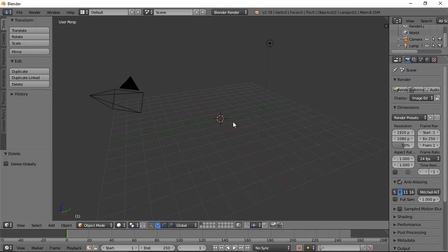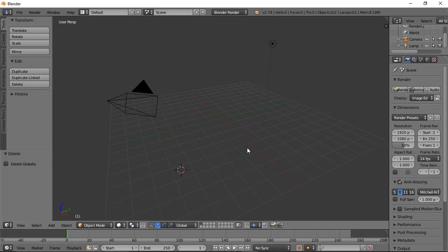Now, if you remember, let us put our 3D cursor to the target location where we want to create an object. I put it here. And let us get a better view of the screen. Press Alt, left click and drag in the direction you want. You see, we have placed the cursor below our grid sheet. So let us again shift our cursor above the grid sheet by left click. This looks fine. Now let us again change our view.